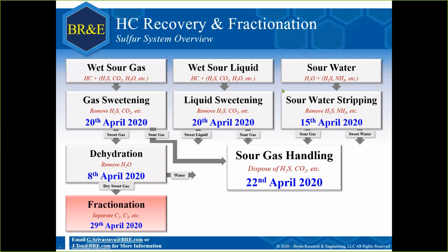We have talked about stripping out any acid gases and ammonia during our sour water stripping webinar, removing water to prevent hydrate formation in our dehydration webinar, as well as how to dispose of this H2S when we talked about SRUs. Today, we have extremely clean gas, very little water, very little H2S and CO2, and we're talking about fractionation and hydrocarbon recovery.